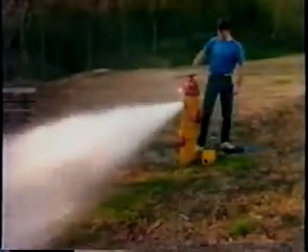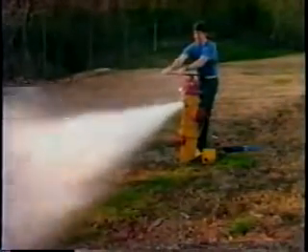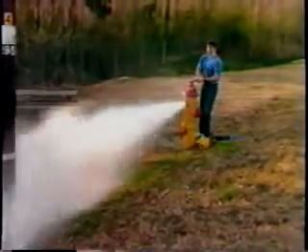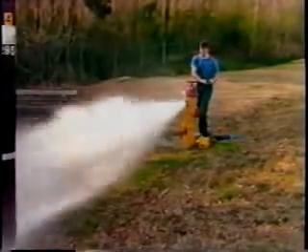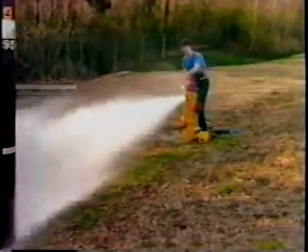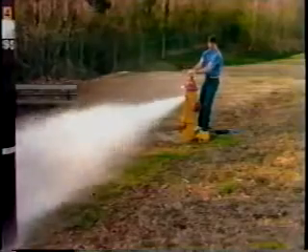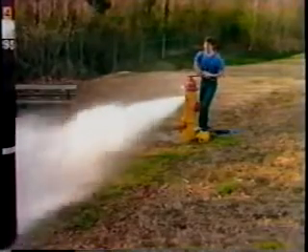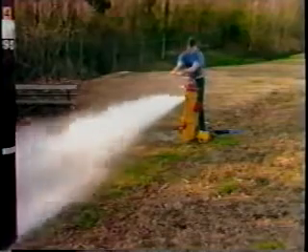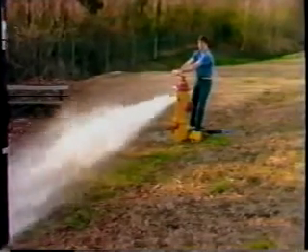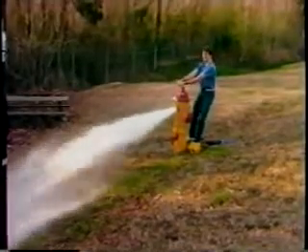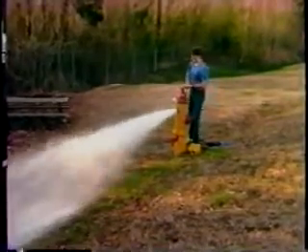When the individual at the residual hydrant is satisfied that the flow test is complete, he will signal to the person at the float hydrant to shut off the hydrant. Remember, just as you had to open the hydrant very slowly to prevent any surges in the distribution system, you also need to close the hydrant very slowly. The last few turns of the operating nut are especially important. Make sure that you do them slowly, or even stop periodically while you're shutting off the hydrant.